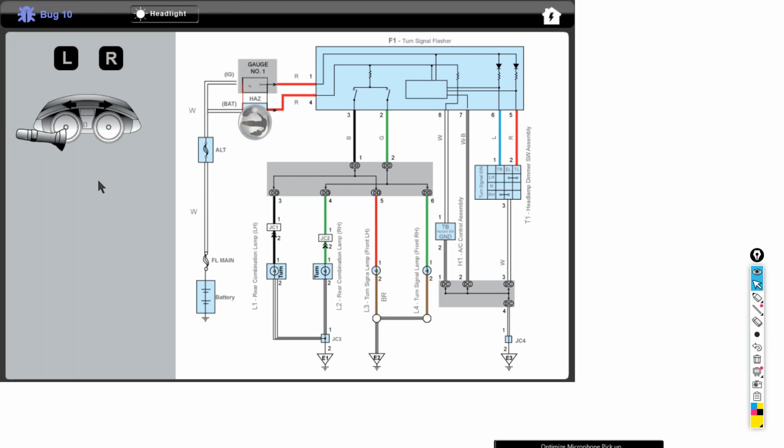We've got a blown fuse, put this tool in there. And by having that tool in there, you can test for a short and you will not damage any wires. So you don't want to put oversized circuit breakers or anything in there to overheat the wiring. Let me give you an example of one of the tools we have here.